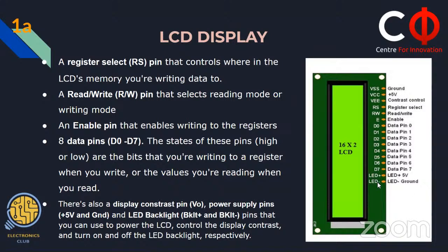The last two pins are quite simple. They are the backlight LEDs. The first will be connected to +5 volt, the power, and the last one will be connected to ground.